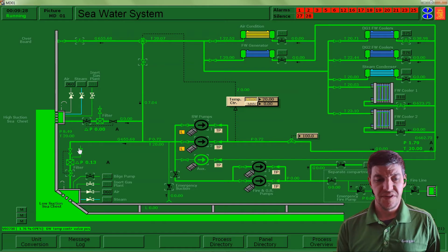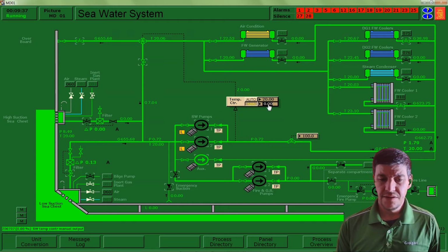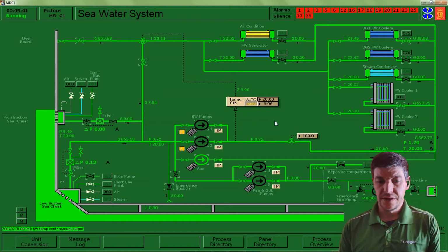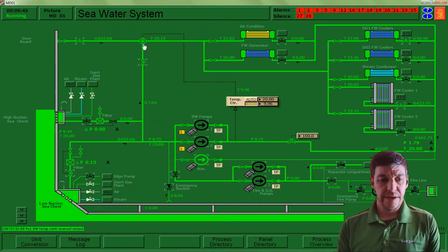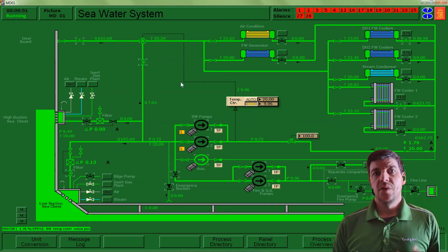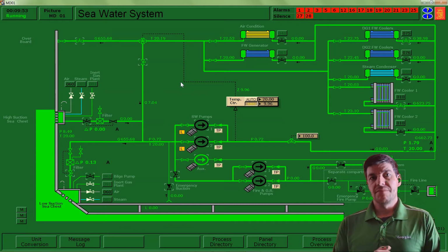So this valve here we see is stuck in an open position at 1.76% open. And if I manually adjust this, so if I set it to say 10% open, and we come back to this valve, we see it's not responsive to that signal. And that valve is missing something. And we think about what could be wrong with that valve, and maybe there's something wrong with the controller.